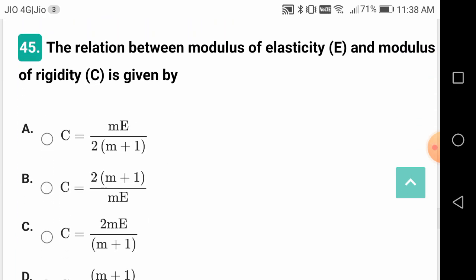In case of bending, the stress is directly proportional to the distance from the neutral axis. Outermost fibers will be at the longest distance, so they will have the highest stress at the top fiber and bottom-most fiber. But their nature is different: compressive on one side and tensile on the other, depending upon the direction of the load applied.